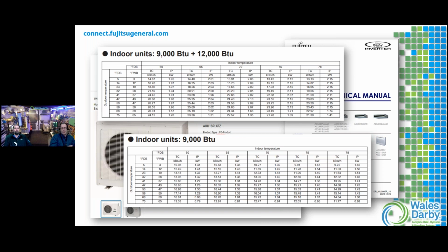And then you can go to the individual units and you'll see what their performances are. Squeaky wheel gets the grease. So your loads are tight, I'm near my set point, the other unit turns on, it's maybe a wider delta. I'm going to shift the refrigerant, load shift, and send it over there. So it's constantly monitoring, opening and closing EEVs, but the outdoor unit is 24,000. That's all it will always be.